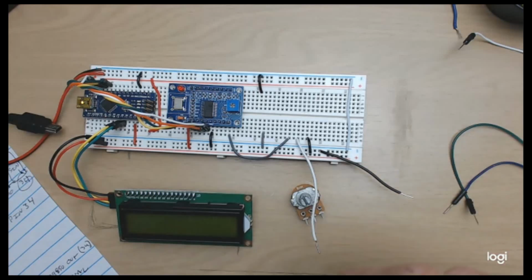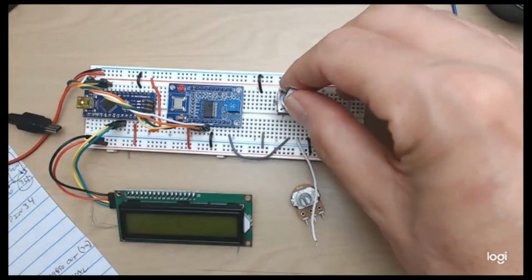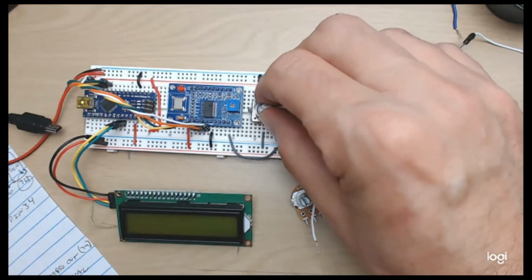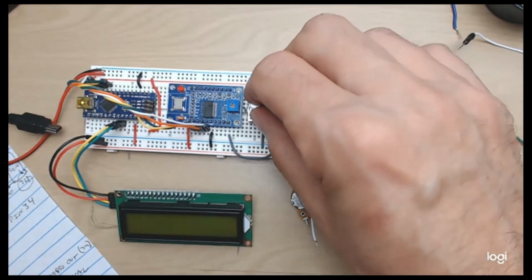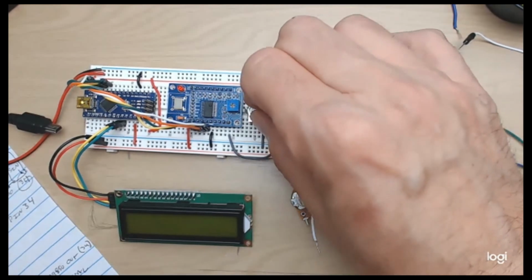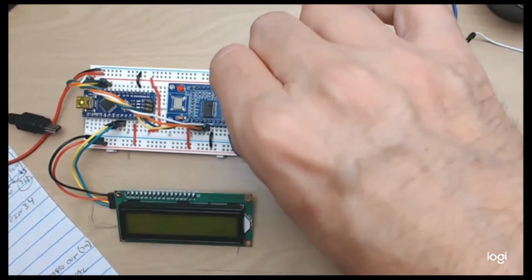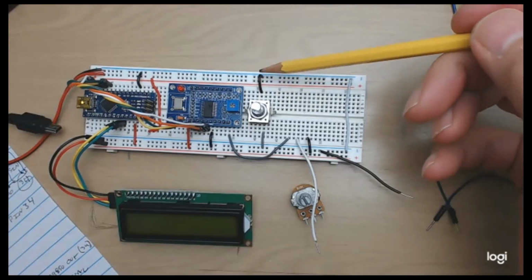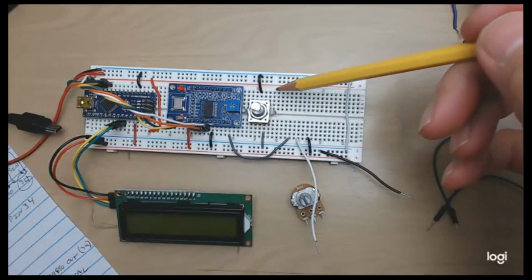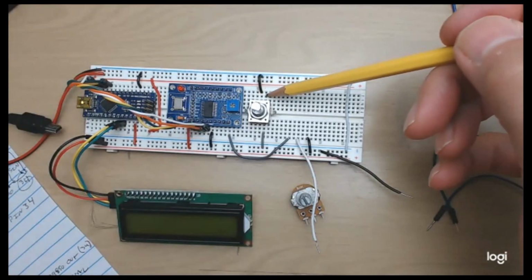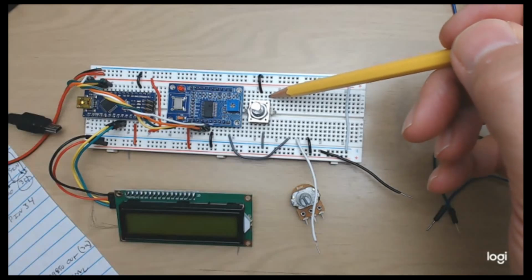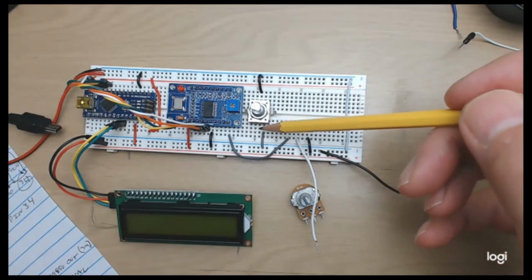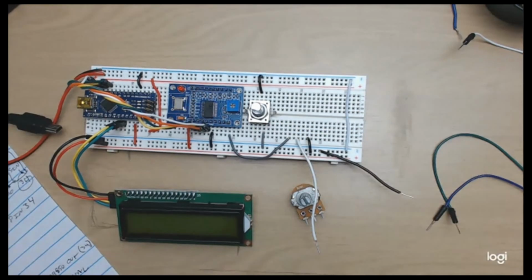All right, so let me make sure I get this in the right place. Again, it would be easier to do if I added the wires later, but I want to make sure I connect to the correct pins and the correct wires. All right, so I think I'm right there. So the black wire on this side is connecting ground to the encoder side of the control. The gray wire here is connecting ground to the button, to the switch.